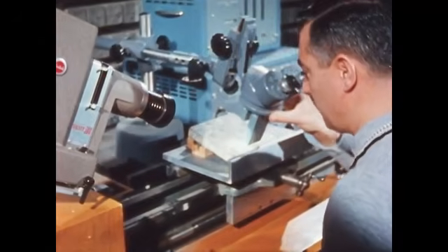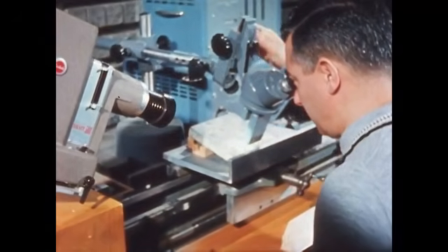Under a microscope, you can see the outline of the entrained air bubbles. Those at the left appear as depressions or pockmarks. This concrete has about 5% entrained air. The concrete at the right has very little air.